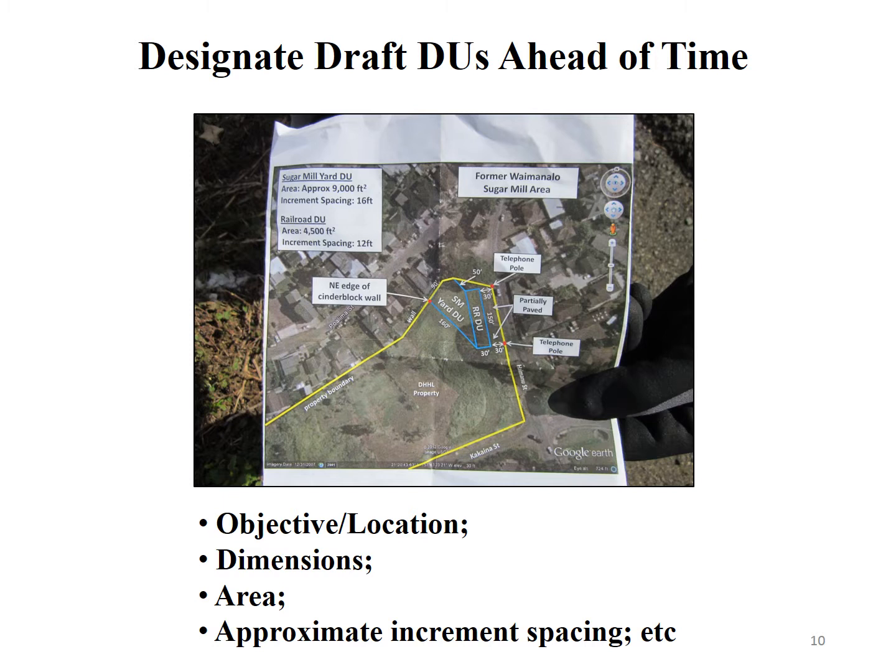Assuming that a thorough Phase 1 environmental site assessment or historical review of property being investigated has been completed, and an initial site reconnaissance visit has been completed, proposed DU locations can be designated and drawn on aerial maps of the site before the sampling takes place. These can then be confirmed and adjusted as necessary during the sampling event.